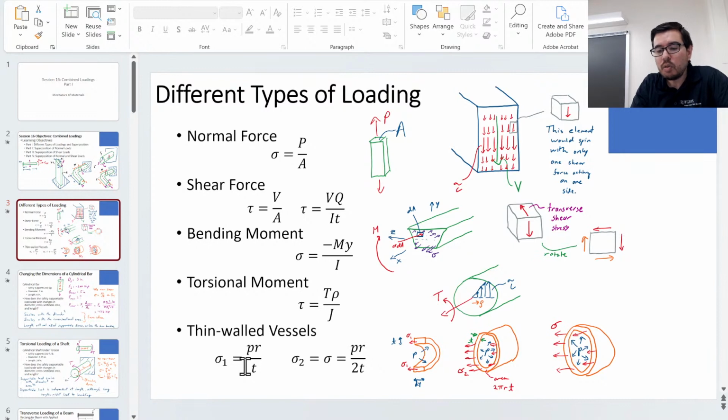There are 2 ways we've discussed to get shear stresses. One is in a beam with the shear force across that beam, thinking about the average shear stress, or the local transverse shear stress with the VQ over It. We've got some experience with that. That is pretty involved sometimes. And we have the twisting of a rod, typically circular, but it doesn't have to be circular. We've talked about some other shapes that you might encounter. Those are the two ways to get the shear stresses.